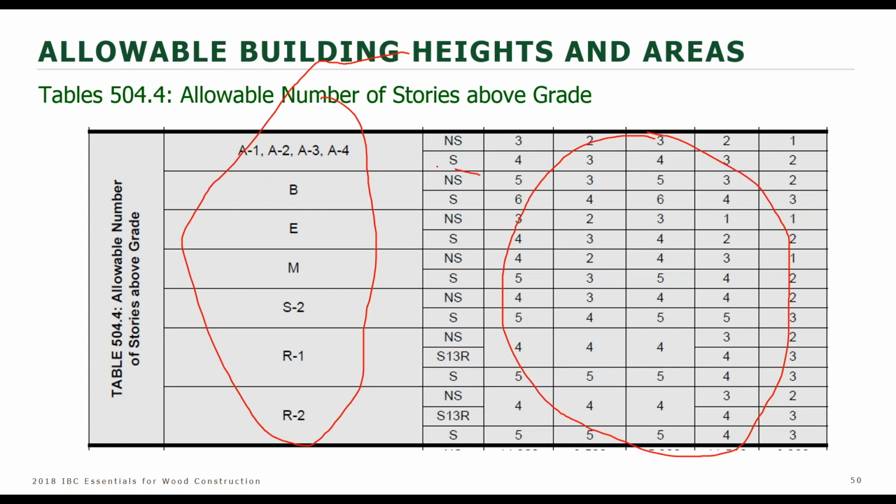And then this is the thing that we have to plug into these formulas right away. It stands for non-sprinklered, and this is sprinklered. So this row here, we're gonna use in the formulas. When it comes to R2, you even have it in R2, non-sprinklered, but we know, if you don't know already, that all R's are required to be sprinklered. So what's that row doing there?